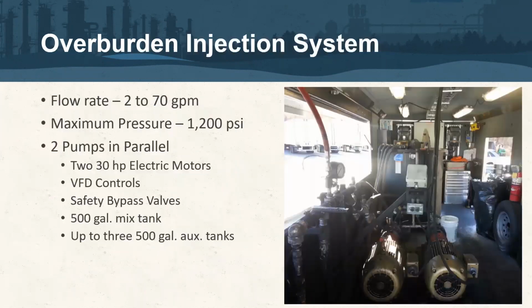Injection of Fluoro-Sorb as a true slurry is going to require higher flow rates. You can see that, and the pressure is called out there. I would note that max pressure line, that is PSIG, so that is of the system. In situ, you're going to see a much different effect of PSI on the formation, and that's just due to system losses, hosing, etc., effect and pressure of the formation. But this system here is necessary, again, because we are moving a very viscous material and because we're trying to affect it on geology in situ, i.e. putting a solid into a solid.